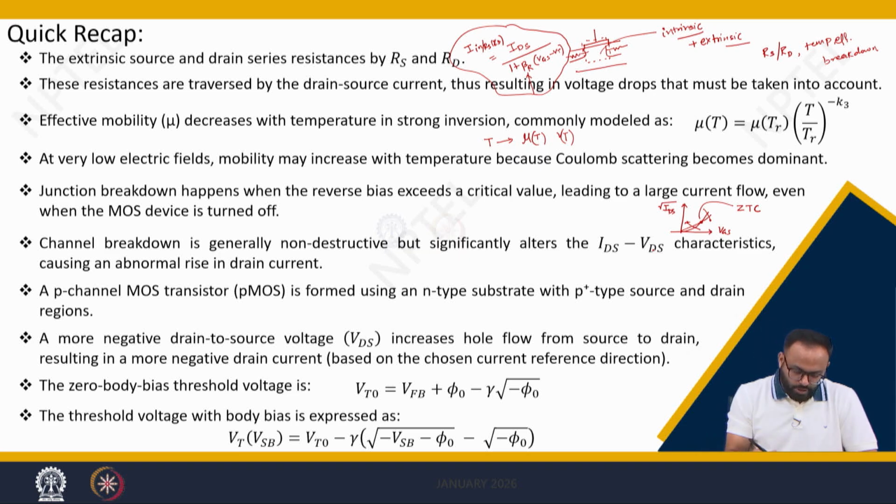In addition, we have also discussed a new flavor of MOS transistor, which we call the p-channel MOS transistor or PMOS. This is nothing but a flipped polarity NMOS transistor, meaning all the phenomena we have derived so far based on surface potential, charge and terminal voltages are valid for the p-channel MOS transistor as well, but you need to flip the polarity of the terminal voltages and currents.